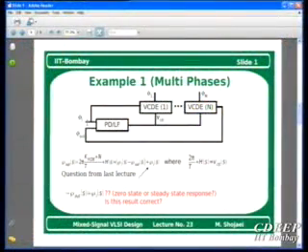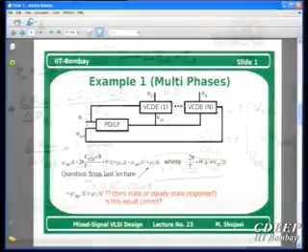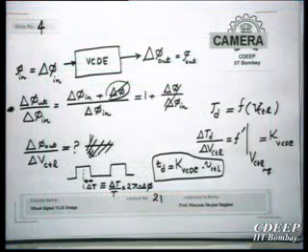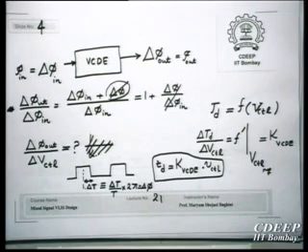Suppose in this scheme I make an abrupt change in our input phase. Now the input phase changes instantaneously by some amount. I have considered that my delay elements don't have any latency. If you remember from the last lecture, if I have any change in input phase, that will be directly transferred to the output phase. This was the characteristic of the delay element. If I change my input phase, my output phase also will change by the same value, because the delay element is giving a constant delay.